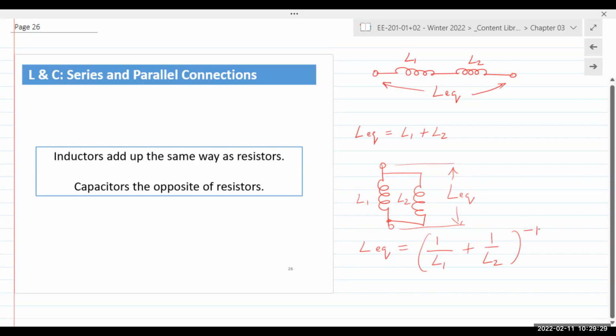Keep in mind, you cannot add up a capacitance to a resistance or a capacitance to an inductance. They are separate quantities. They're physically separate, right? So you cannot add them up. But when we get to chapter 5, we will have impedances of all of these three components, and so there we can actually add those up. If you have impedance for a capacitor and impedance for an inductor, we can add them up, because impedance is the same kind of quantity as resistance. Make sense?